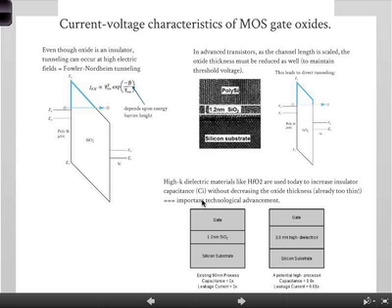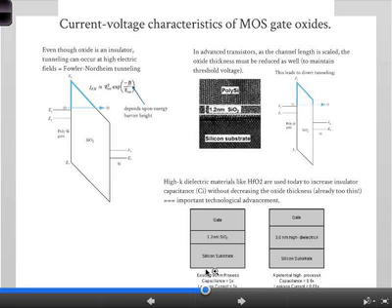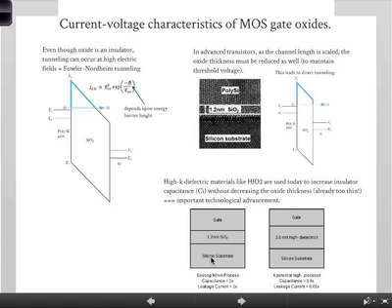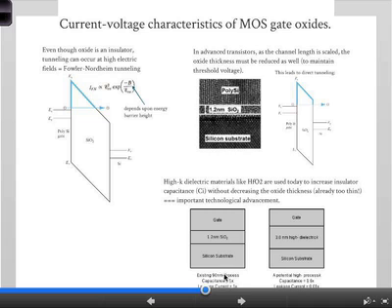So there's an example shown here. So you have a gate, 1.2 nanometer oxide, and the silicon substrate. So okay, this is the 90 nanometer CMOS process. Okay, this is probably 2 or 3 years old now. Nowadays, it's like 32 nanometers, so you can get a sense of progression. And that 90 nanometer, by the way, approximately relates to the length of the channel. So we'll talk more about it in chapter 9.